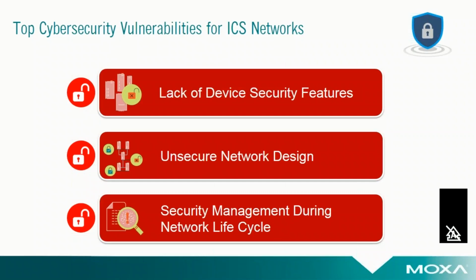Secondly, the network design in many legacy industrial network topologies never considered security protection. In many cases, we'll go into a factory or a plant and see that the control network is one big flat layer 2 network with no segmentation at all.